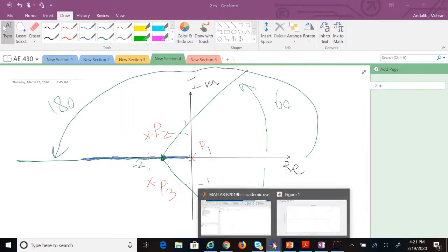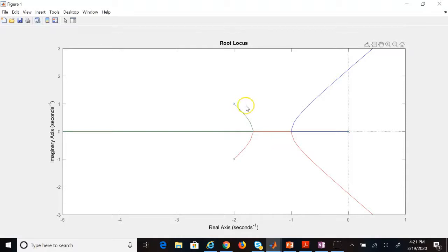And so, again, if I go back to this graph that I just did for you, you clearly see here, if I draw a line tangent to the Root Locus at that point, okay, let me continue it all the way to here, this angle of the Root Locus tangent with respect to the horizontal axis, this angle is what we call what? The angle of arrival, okay? I'm sorry, departure. This is the angle at which the Root Locus branch, this green one, is departing that complex pole.